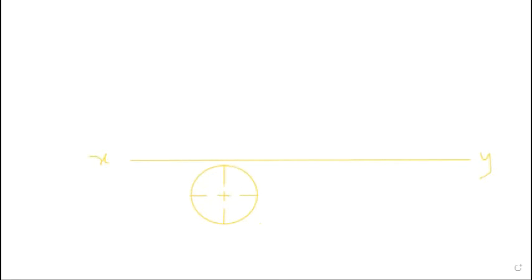Okay. Now from each point we draw the projection, and here also draw the projection. The height from the XY line will be 60 millimeter because it is 60 millimeter height and axis vertical. So this is the front view and top view. And here also we divide the circle into 8 equal parts.